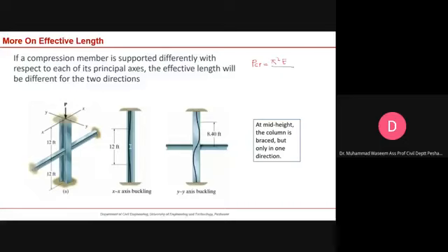We have this type of formulation of the critical stresses. I hope I have not missed any superscript or subscript, but this is the Euler formulation, and with its help we can estimate the critical load or critical stresses in the compression member.